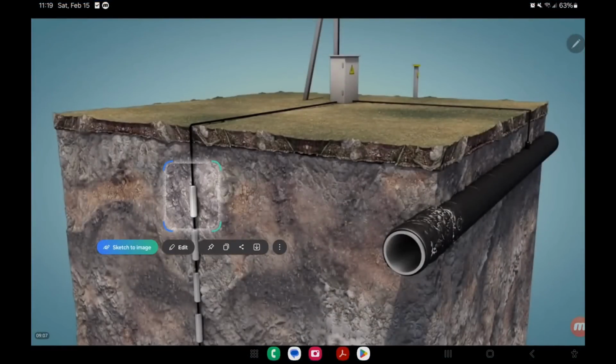They call these chemical bars. They are simply anodes: magnesium, zinc, aluminum, or ferrosilicon chrome. When we, the corrosion specialists, select specialized materials, our purpose is for them to be resistant to current discharges, so that we design for 20, 30 years, and we estimate in our calculations how long that material will last.